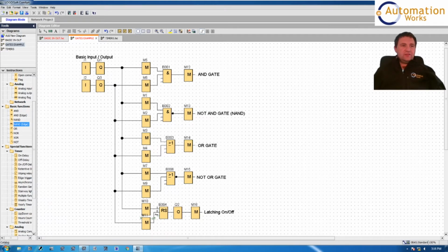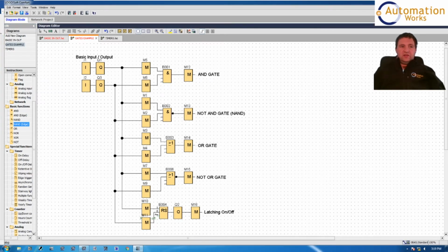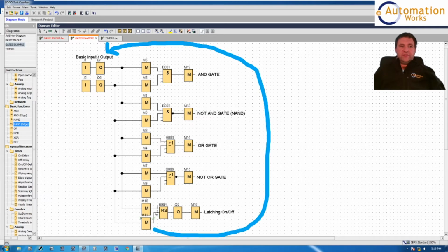To understand these functions, you need to understand how the instructions in a PLC are executed. The PLC starts with the first instruction and runs through all the instructions on the page until it has done each one once, at which point it starts back from the top again. This is called a scan cycle. The rising edge will output a 1 if all the inputs are 1, but only for one scan cycle. On the next scan cycle, it will be 0 again. This is called a rising edge detection.